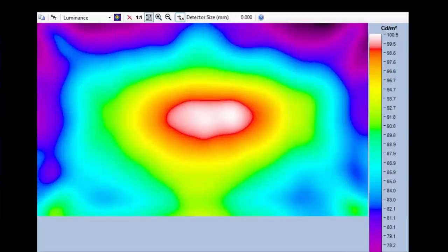Simple point-to-point luminance comparison isn't enough. We need to figure out what the human eye is good at seeing and what it's not good at seeing. So this is the contrast image comparing the original image to the reference image, which makes it easier for our image processing routines to find that particular line and highlight it. And that's a lot of the pre-processing that we do in order to do the Mura.